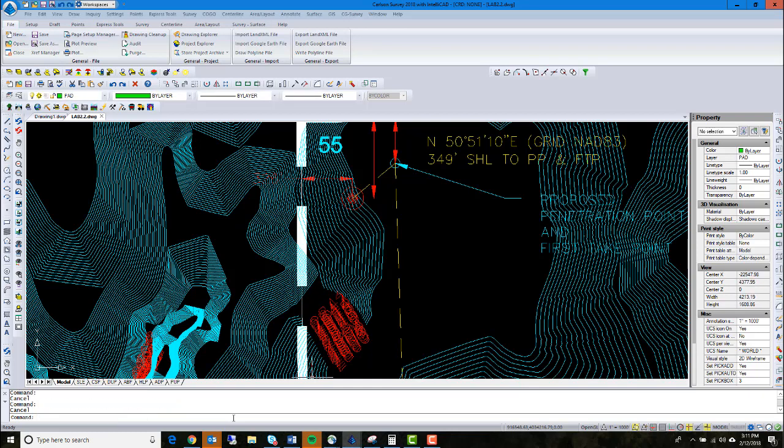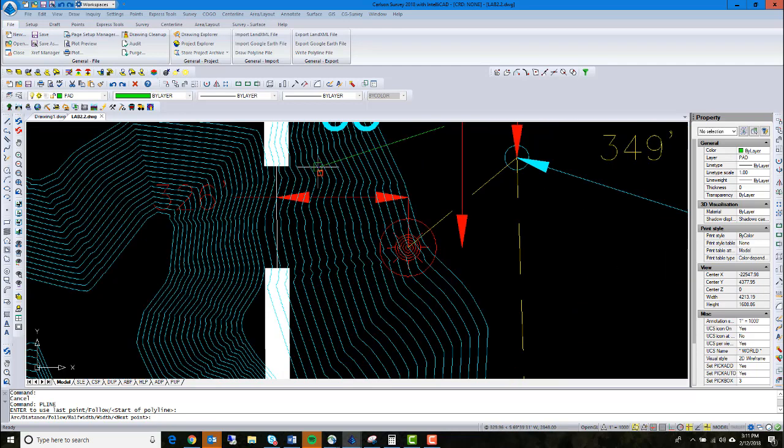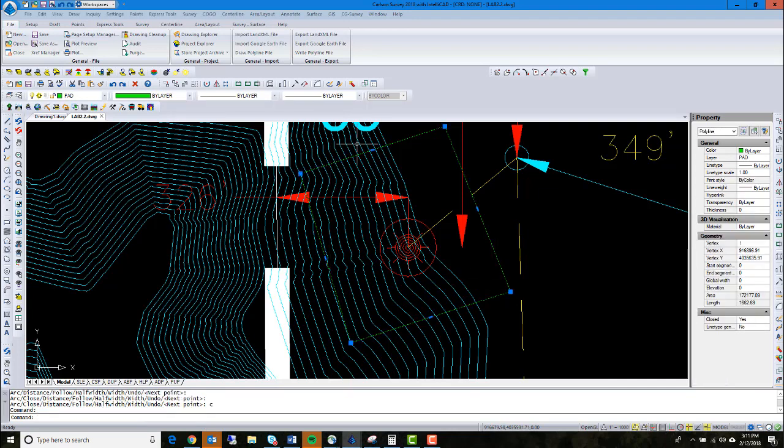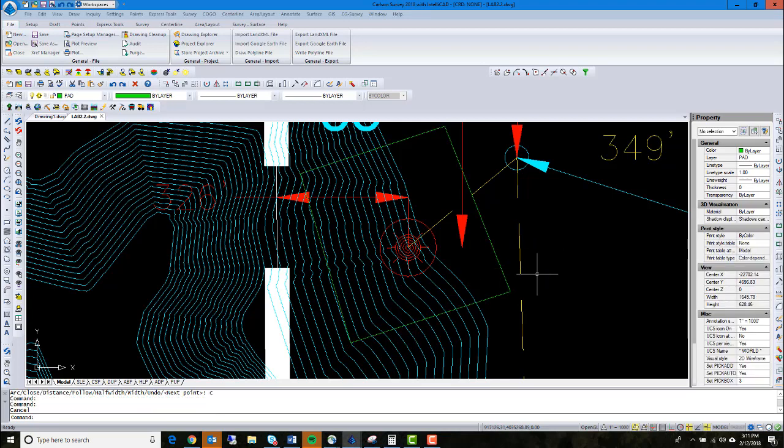pad. So you can hit escape here, and I could just say P line, okay, and hit enter, and it says where do you want to draw it, and I can go here. If it's, see that red box is trying to snap to the line there, you could snap to the line, that's fine. I'm just going to draw a quick rectangle, come over here, and to close it I could come up here and snap onto it, or I can hit C for close, and you can see C shows up down here, and I just hit enter and it closed. Now I have a closed polygon. If I click on it, it has the nodes all around it showing it's a closed polygon.